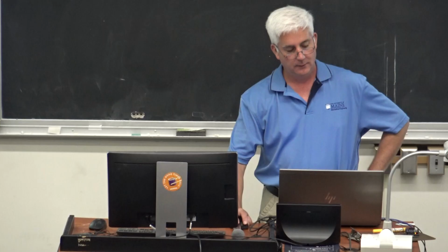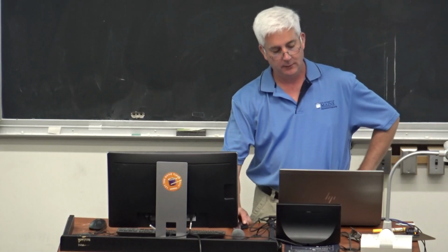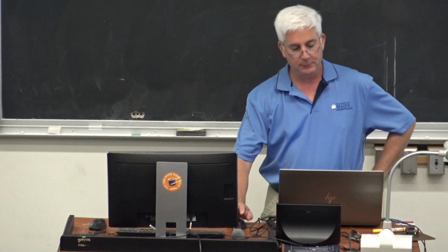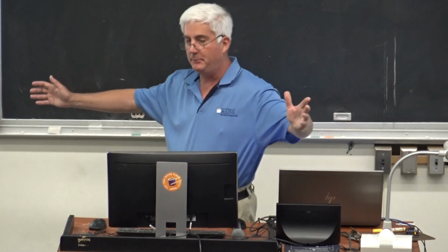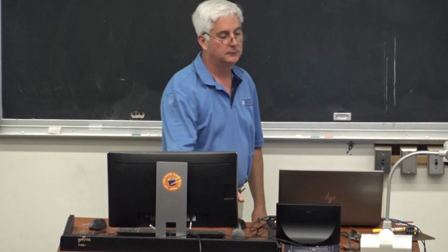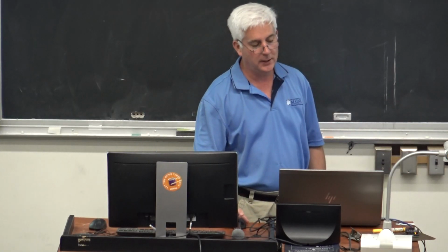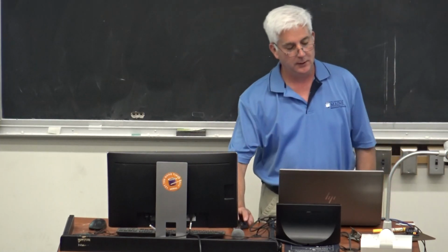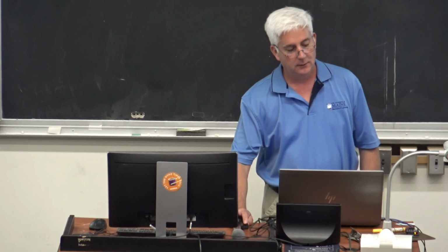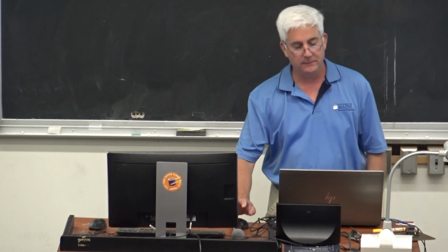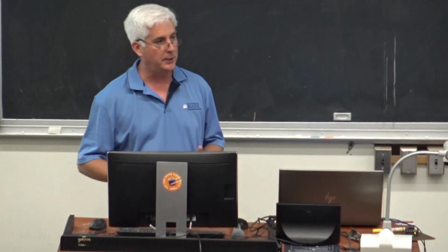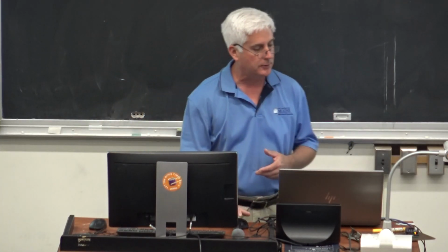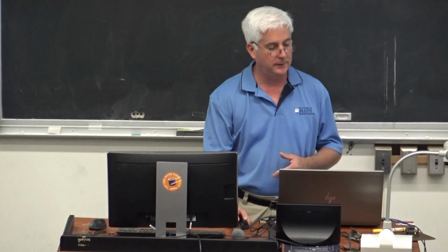Next, we'll come down to the port. So when I plug that in, it says, aha, I see a Mega on COM6. Great. Make sure that's clicked. And now, up here, this is verify. So if you just want to check your code, make sure it compiles properly into machine language, you can hit that.